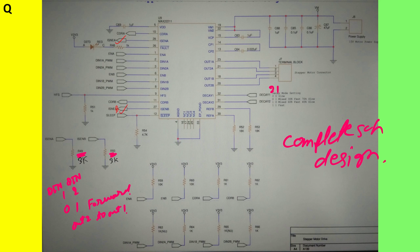As you can see, for isense A I have put a resistor of 3 kilo ohm, and for isense B also a resistor of 3 kilo ohm, and similarly this isense A and isense B will be taken to the MCU ADC pin. But before giving it to the ADC pin, you have to go for a buffer circuit. Let's say this is your isense, and this will be a buffer, and then you put it to the ADC pin. Got it? That I will be showing you in our microcontroller section. These are all assignments of the pins in here.